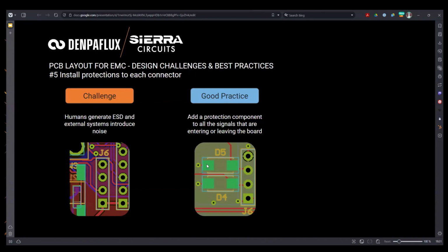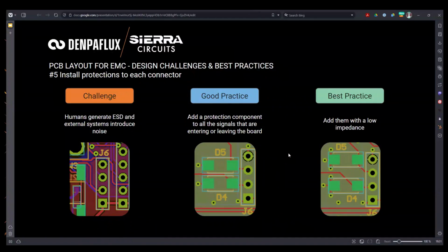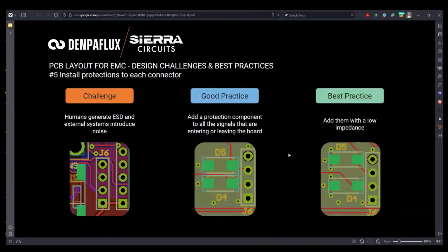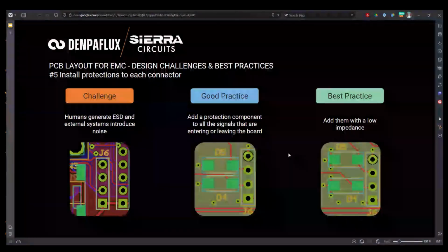But also, same as with the coupling capacitors, the connection from the components to the return point, normally ground or the mechanical case, needs to be very, very short. We do that again by placing vias very close to the pin. To make it very efficient, that parasitic inductance needs to be as low as possible. In protection elements, this is very important. So one via is good, three are better, so that we guarantee a very, very low inductance.